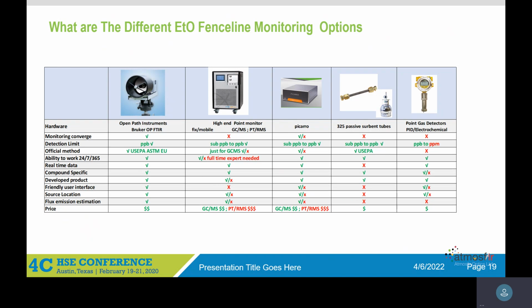And either you can drive around or you can do multiple tubing. Those are quite problematic when we're talking about ethylene oxide. First of all, it's very soluble in water, so you need to do a lot of fence line. Now take 1 kilometer of fence line. We're talking about electricity, we're talking about explosion, and if you've got a cold spot, then the ethylene oxide will absorb in its cold spot. So I will recommend those if you want to do one source, but don't go all around the facility with tubing. A lot of problems can go with these things.